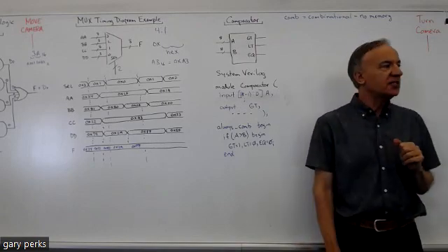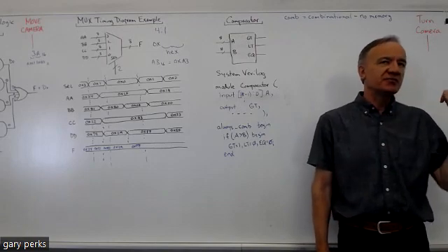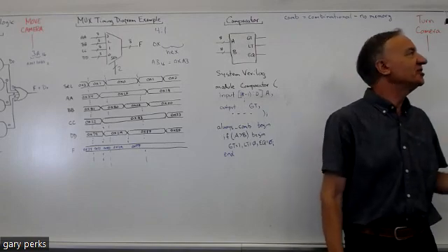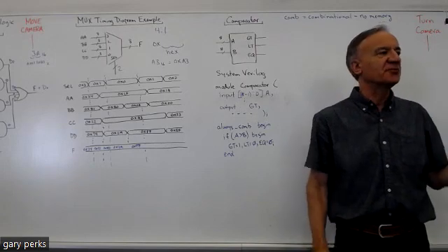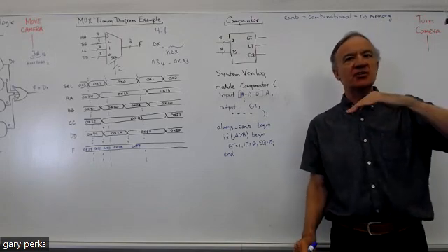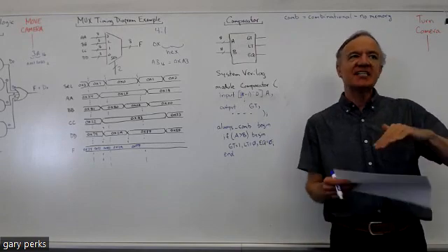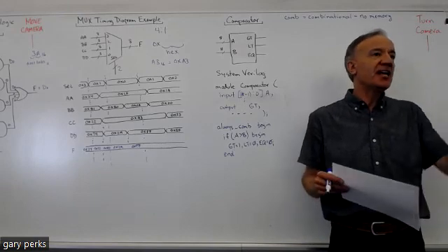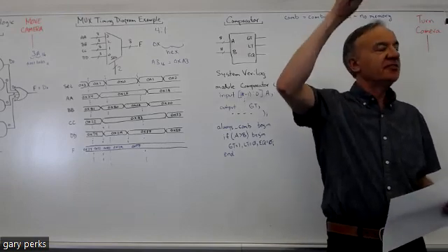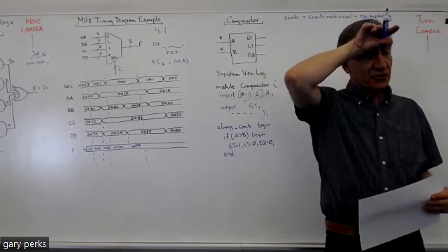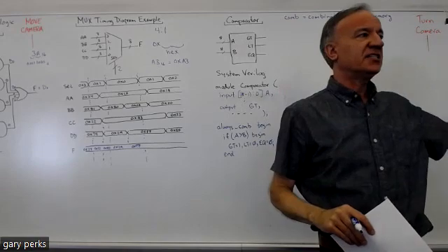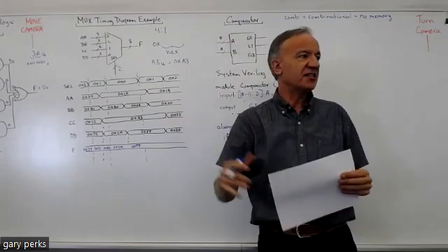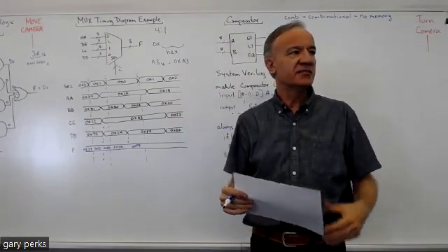See, this is an always_comb. There's also just an always block that we'll also talk about in a little bit. And there's also what's called an always_ff, which has to do with sequential circuits that we'll get to in a few weeks. But any kind of always block, you cannot have an assign statement. Assign statements are only outside always blocks. And you can have assign statements in your structural model. In fact, that's usually where you put them, just like you saw in the activity last class, where you had the code making connections, but then there'd be an assign, like if you had a gate or something. That's typically how it's done.